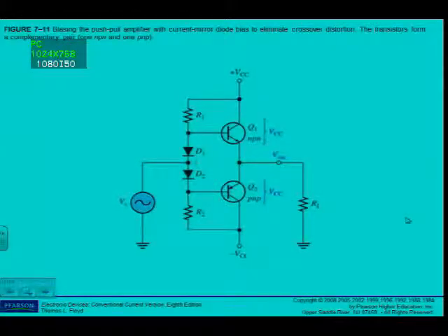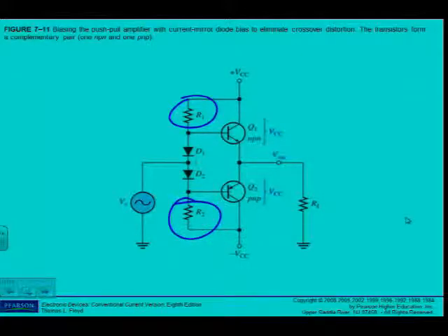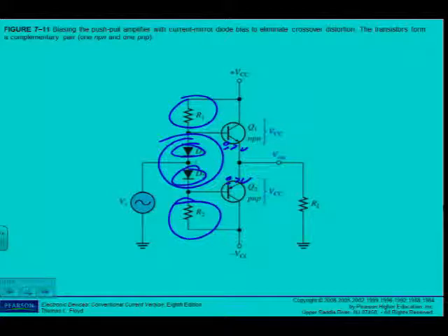Remember in the introductory paragraph we said it's difficult to do this. Why is this difficult? See what I've done. I've done some biasing. I've got the voltage divider here again. But I'm also using two diodes. What was the problem? The 0.7 volts here. What is the volt drop over a diode that is forward biased? 0.7 volts. But what do we know? It's not exactly 0.7 volts. And that's where the difficulty comes in. I have to find a transistor and a diode which has approximately the same voltage drop over the forward biased PN junction. That's where the difficulty comes in.